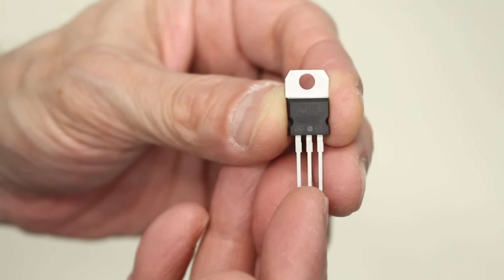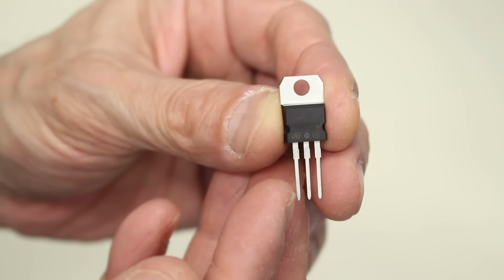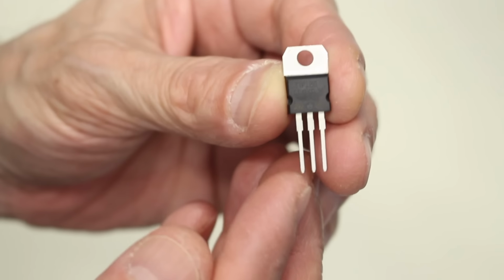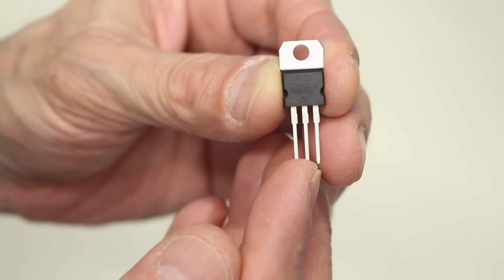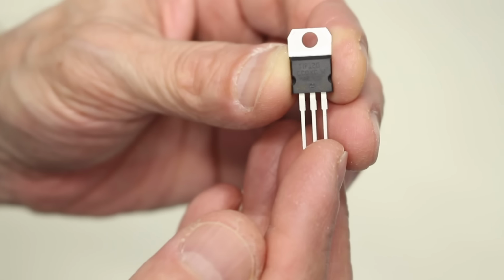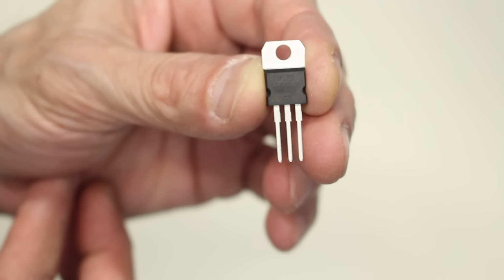Make certain that you don't ground the heatsink or that you use an insulator between the heatsink and the transistor. The pinouts of it are as follows. This pin on the left side is the base. The center pin is the collector. Again, that's the one connected to the tab. And the emitter is the third pin over here. This is the transistor we'll be using in our experiments.